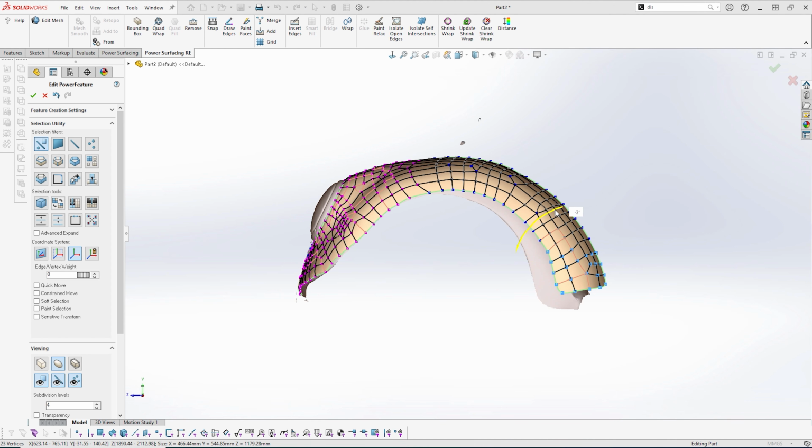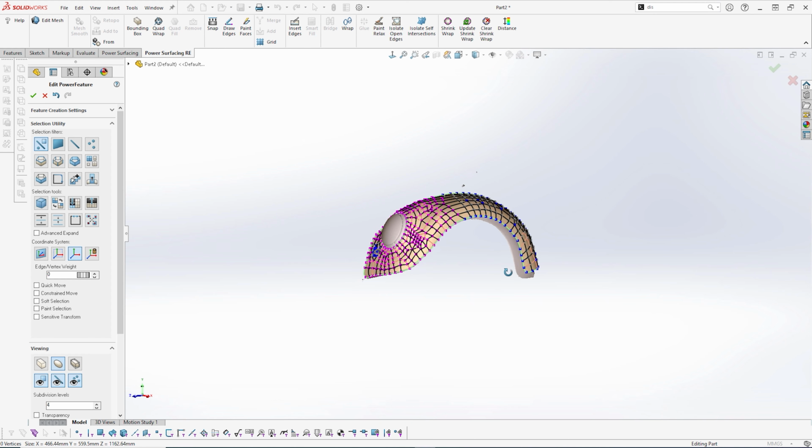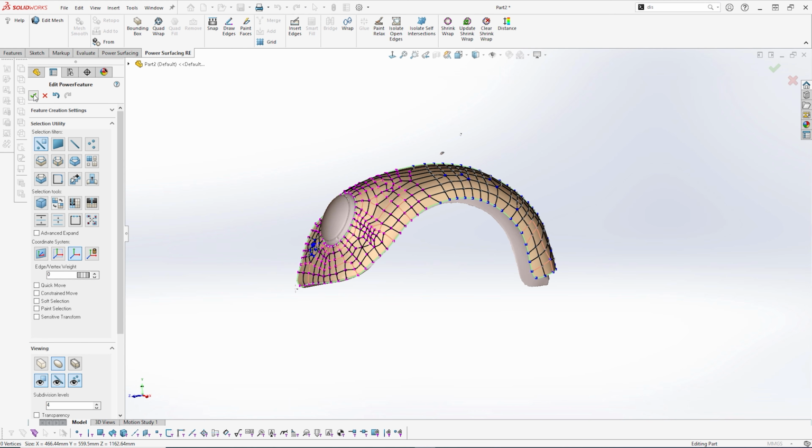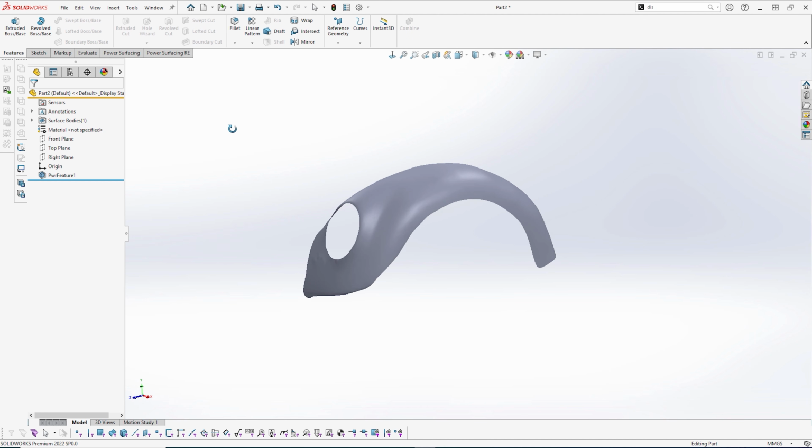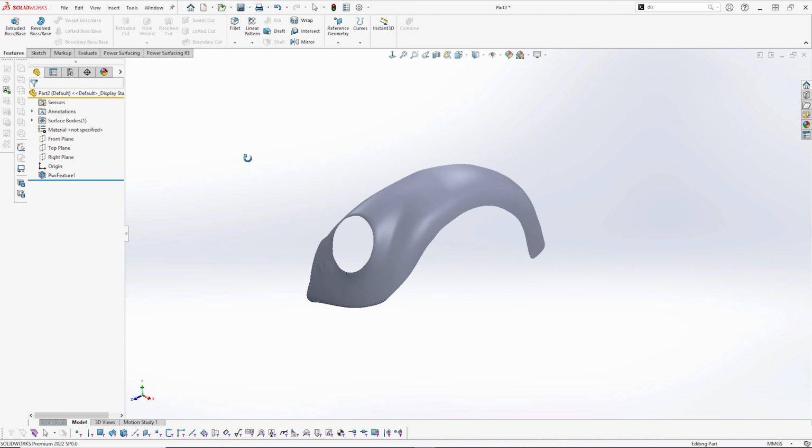Again, you can drag, rotate, you can scale. There's even mirror commands here to make sure you maintain symmetry. All I'm going to do here is a relatively simple change, just maybe elongate it, maybe pull that back end down a little bit, give it another tick. That then generates a brand new surface. And again, it's a normal surface, so we can now use normal SolidWorks commands.